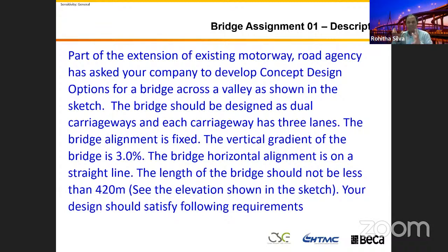The concept design is the bridge, not exactly what they're going to build, but this bridge should be able to be built. You will give them the dimensions of the deck, your girder sizes, slab sizes, cross girder sizes, column sizes, foundation, everything. That's what I said.